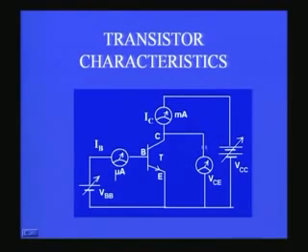So, what we are now doing is basically on the output side, at the collector and the emitter part of the circuit of a transistor, and therefore this is called output characteristics. This is just one example of several characteristics that you can think of in the case of a transistor. For example, you can also have common base characteristics. Again, you will have input characteristics and the output characteristics, but the transistor will have the base as a common terminal between the left and the right side, the input and the output side. Similarly, you can have common collector characteristics and things like that.